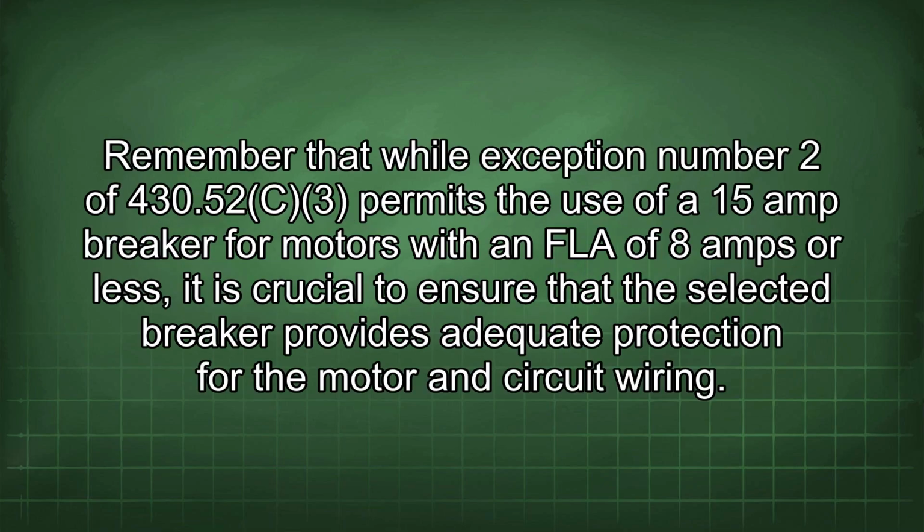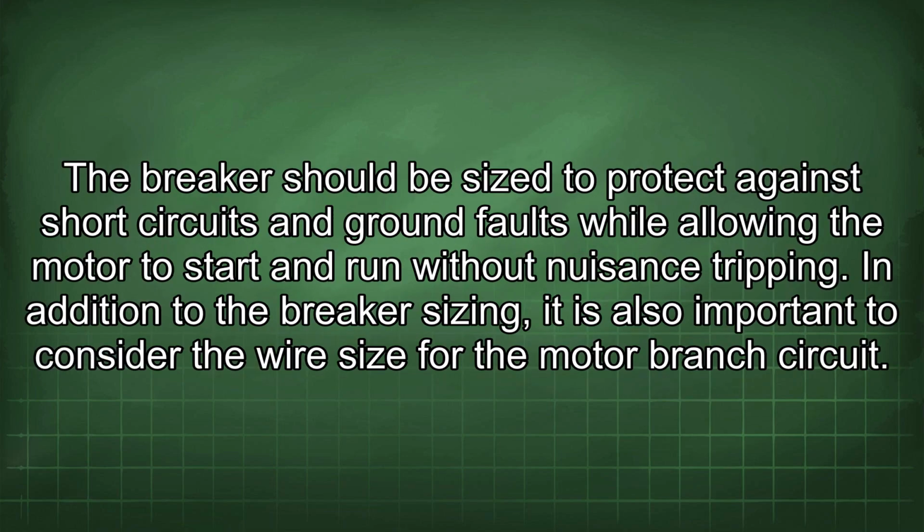Remember that while Exception No. 2 of 430.52(C)(3) permits the use of a 15 amp breaker for motors with an FLA of 8 amps or less, it is crucial to ensure that the selected breaker provides adequate protection for the motor and circuit wiring. The breaker should be sized to protect against short circuits and ground faults while allowing the motor to start and run without nuisance tripping.